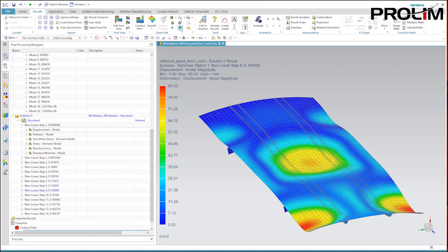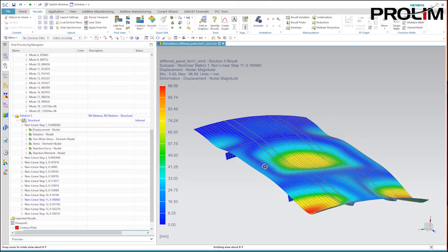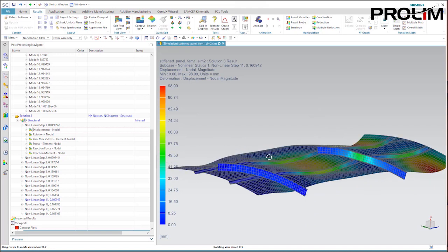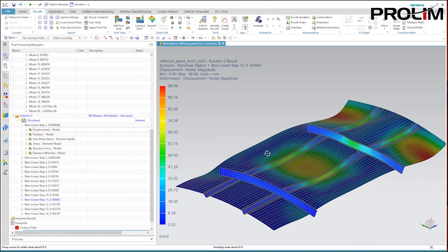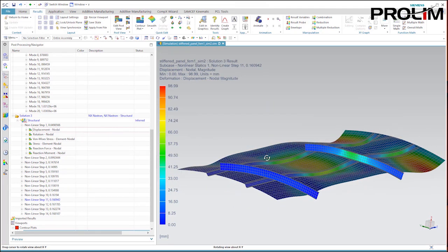The main reason buckling is following a given path rather than another is the existence of geometric imperfection. A proper way to take into account such imperfection in the simulation is to use a mode shape, specifically the one reproducing the right imperfection.